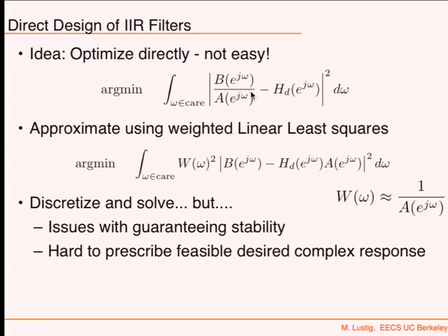They are implementable. These are represented as recursive filters, right? So they are implementable, and they are actually very efficient. In fact, when you have a recursive filter, you basically save a lot of computation. You don't have to go and compute what you already computed. This is why people use IIR, because with less computation you can get sharper transitions, for example. It's not as much of an issue today with computation, but if you have a system that is limited by computation, then IIR might actually be your solution if you don't care about nonlinear phase.